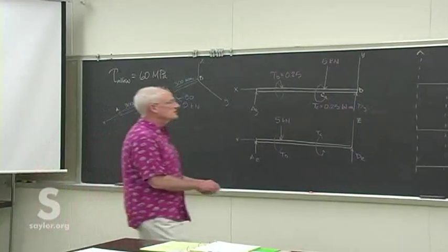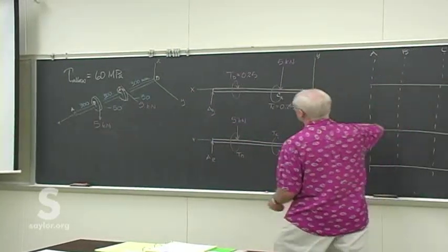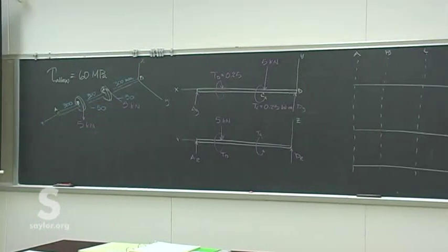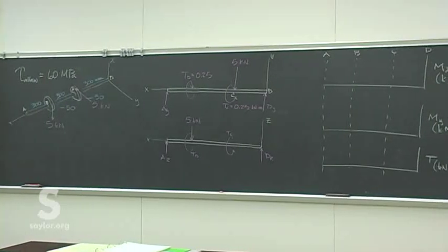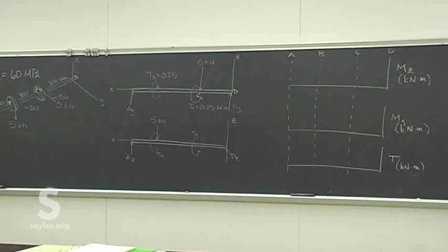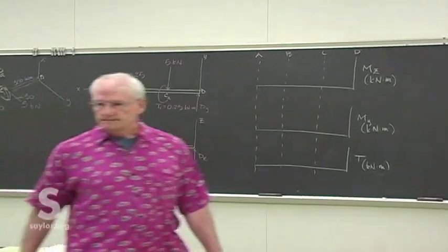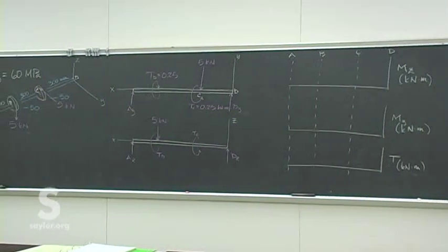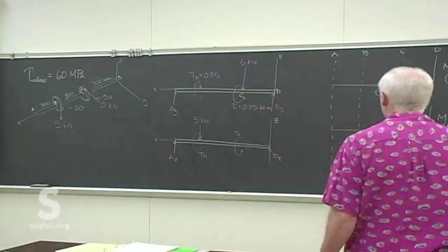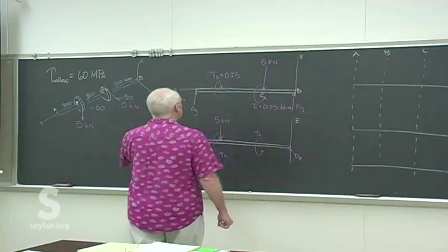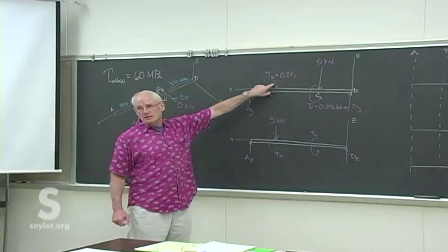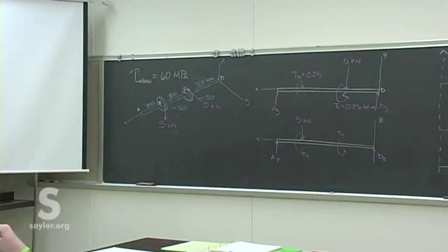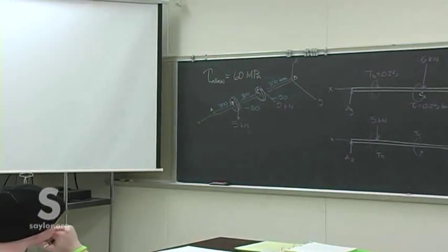Okay, so come up with these drawings here where we show the torque, the moment at different places. I think it's a little easier making them above and below each other. Just a little bit less chance of making errors. Remember, for the moment diagrams, the torsions don't apply, and then for the torsion diagram, the moments don't apply. That's all right? Thank you.